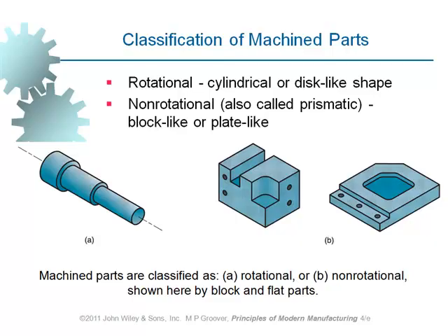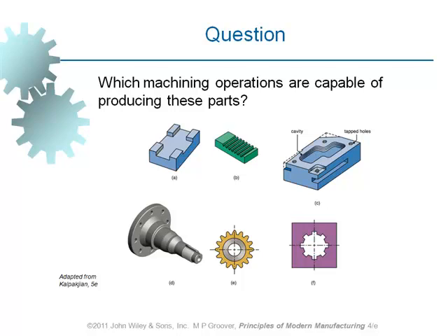But of course, milling is a well-known process which can be used in order to bring this part to final shape and geometry. For example, here we've got some other types of parts. The one at D, it's easy to say which method can be used to make it. We've got to make use of a lathe to make it, but still we've got to make use of some other machines in order to machine some of the features on it. For example, as you can see up here, there is a slot. You see the slot right here.